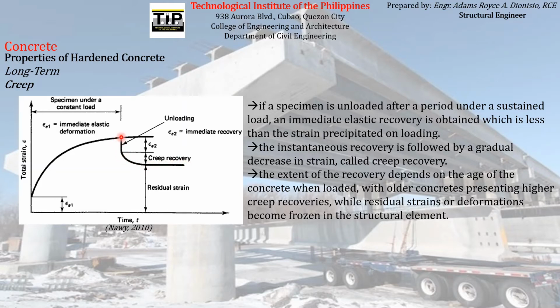And again, that sudden decrease in the strain being experienced by the material when you unload it is what we call the immediate elastic recovery. And the gradual decrease in strain following that immediate elastic recovery is what we call the creep recovery.